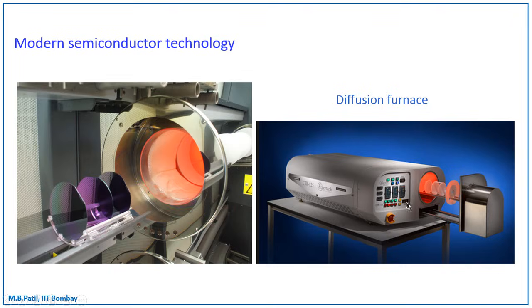There are these controls here to control the temperature as well as the duration of that processing step, and the wafers are stacked over here. So this whole contraption comes out, we stack the wafers and push it in, and here is a close-up. So these are the wafers. They will be pushed into the furnace. The furnace will be locked up for whatever number of minutes, and that is how this diffusion process takes place.